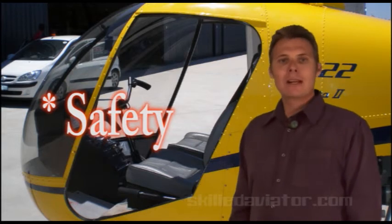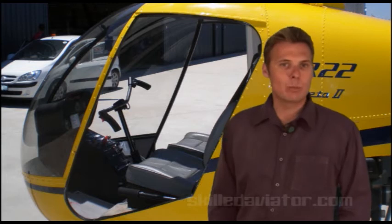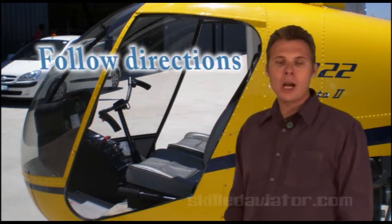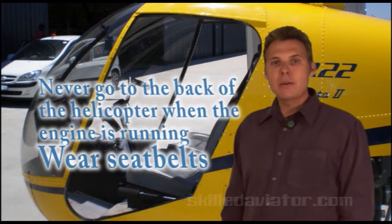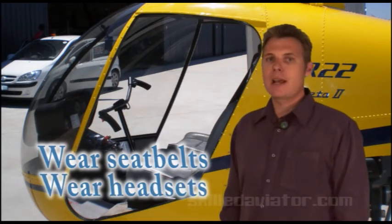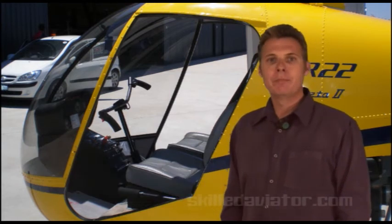Before you go out to the aircraft, we'd just like to give you a briefing to ensure that you have a safe experience. Follow the direction of your instructor at all times. Never walk to the back of a helicopter with its engine running. Seatbelts are to be worn at all times. Hearing protection should be worn at all times, and you should also be in constant communication with your instructor.